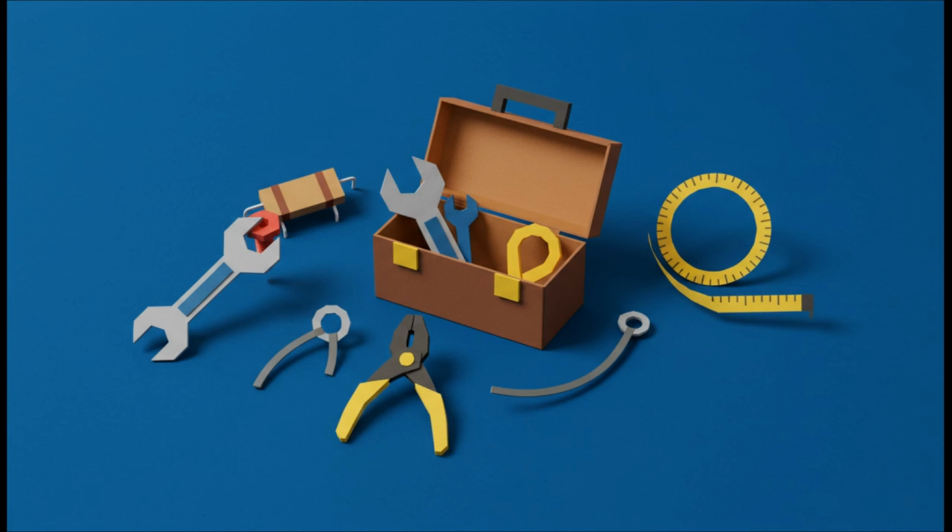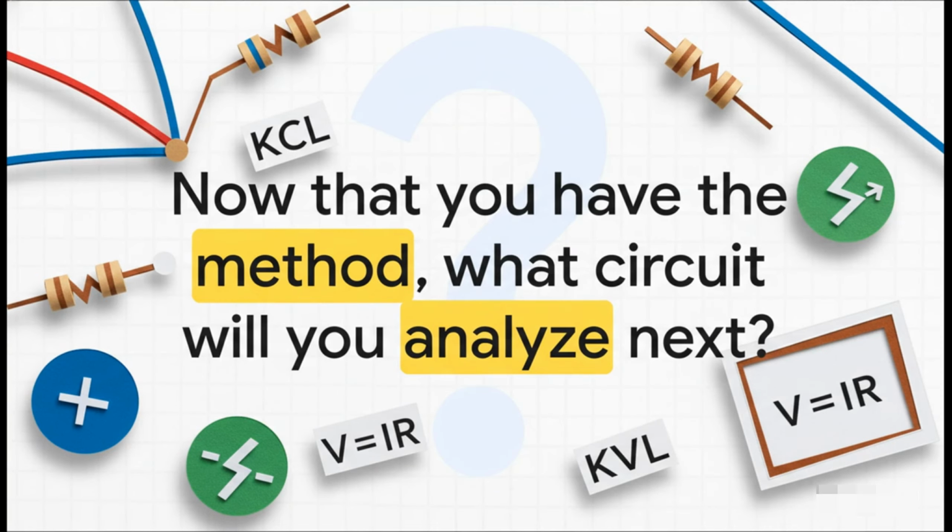Use Ohm's law when you're looking at just one component. Use KCL when you get to a junction, a place where the current splits or comes back together. And you use KVL to check your work by looking at any closed loop. If you can remember what each one is for, you can analyze tons of different circuits. So there you have it, a really clear step-by-step method that you can use again and again. You look at the circuit, you use Ohm's law on the individual parts, you use KCL at the junctions, and you double-check everything with KVL. That's the system.